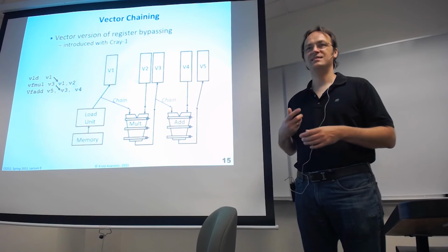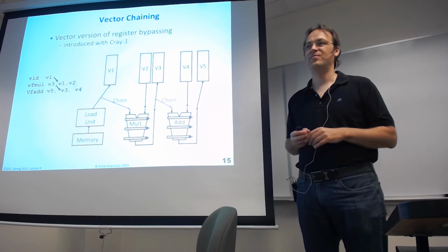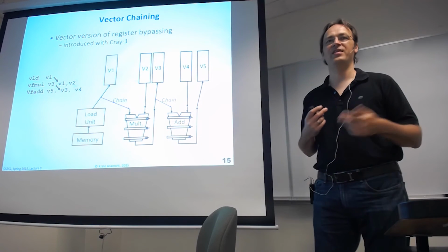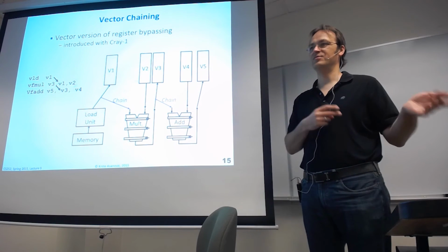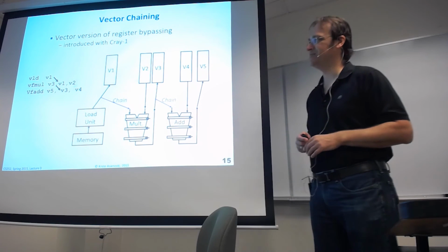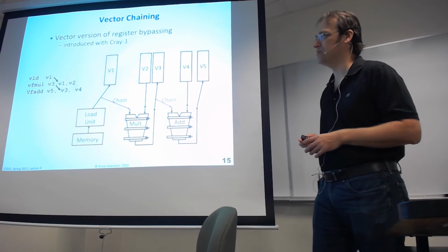The later Cray XMP, they kind of fixed this problem by having real read and write ports on every vector register, but then programmers complained that they couldn't do reductions fast anymore, so this hack had gone away. But that's what they did. But basically, there's physically only one read or write port in each of these SRAMs.